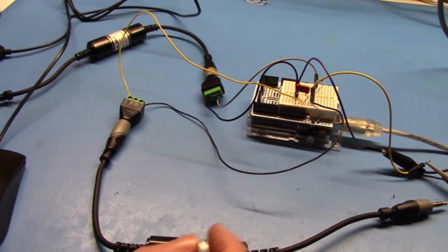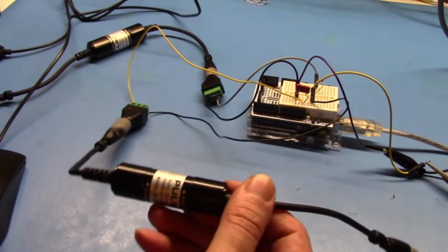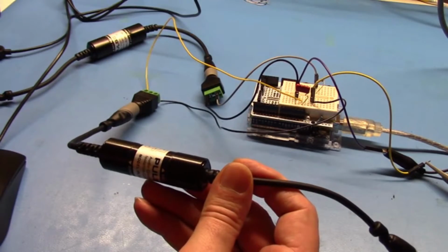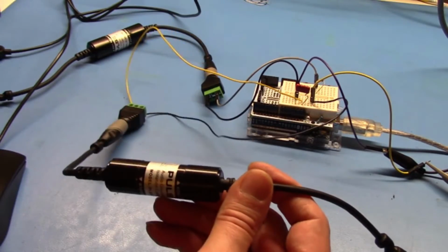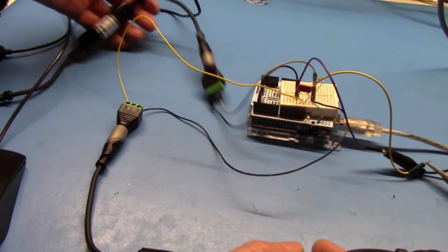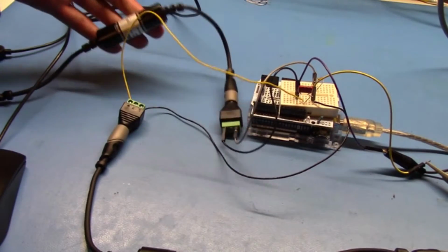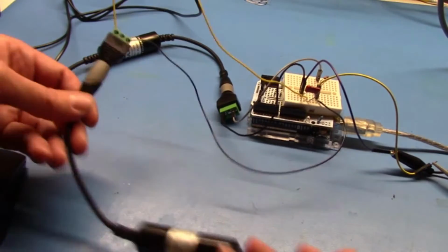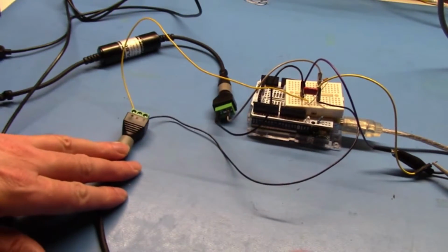Now, I originally tried to use just one of these devices so that the audio would be coupled in through the other windings of the transformer, but I couldn't make this work. So in the end, I'm feeding the audio as before from the PC through one of these transformers, and I'm using the other one connected only on one side to function as an inductor.